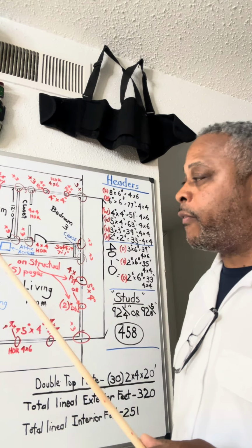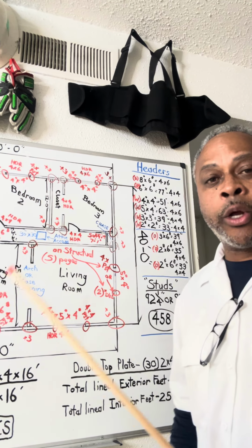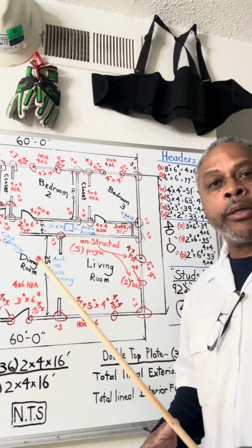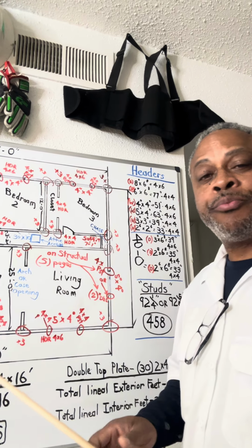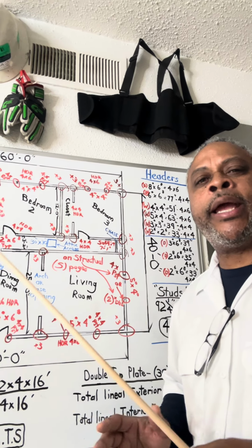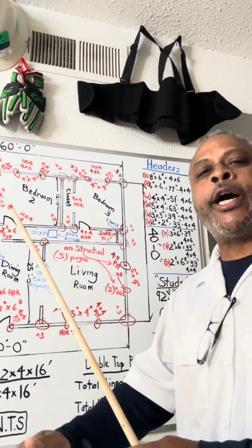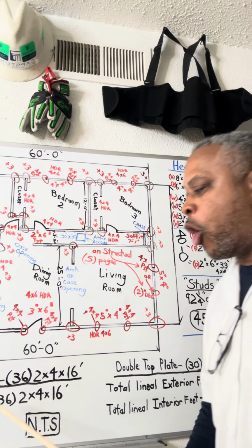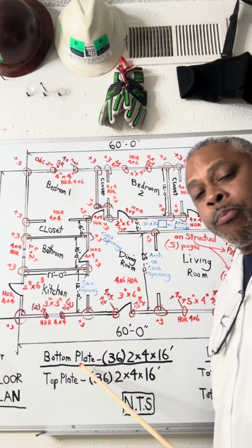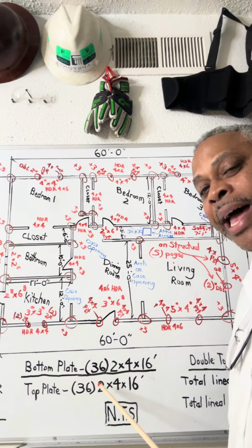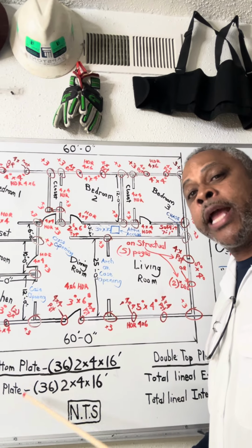Guys can get fired off of a job when they do not take care of the lumber. When you receive your lumber, it's going to come in a very large load for your job site. So you need to itemize, categorize and separate your lumber. You need your studs by themselves. You need all your plating because you're going to be starting from the bottom. And this bottom plate has a certain size to it. My top plate and my bottom plate are the same size.